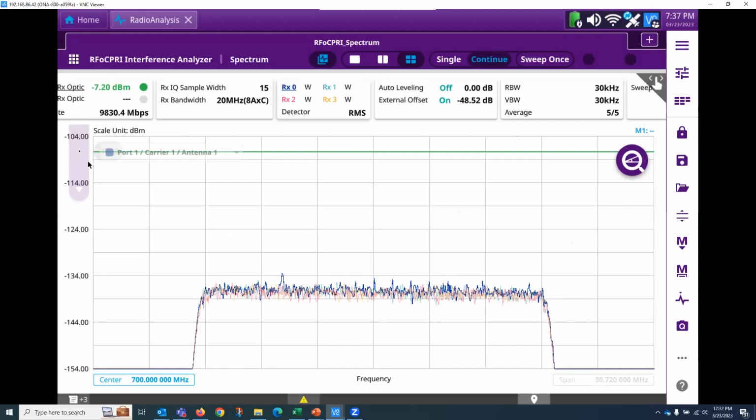It's an extremely simplistic system, as defined by what Eduardo talked about. We tapped into the fiber. We are looking at the system live, and I've had a couple of questions in the background that I've been trying to answer, so thank you for the questions. We're using the antennas that are in the system. The design of this is you've got your RRU or your RRH. There are some questions about LTE versus 5G. If it's CPRI based 5G, this works just as well on 5G as 4G. We'll get into some of the questions as we get to the end of the call, but this allows us to see exactly what the system is showing us.